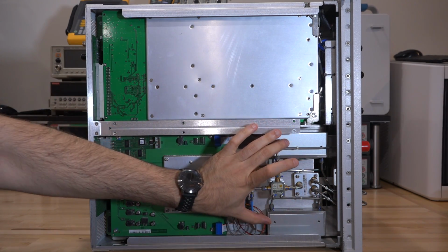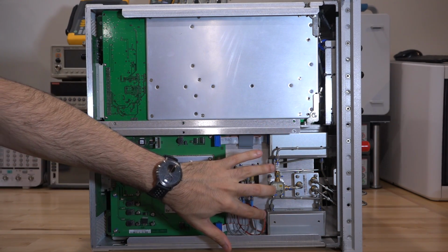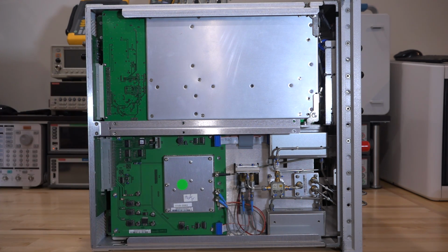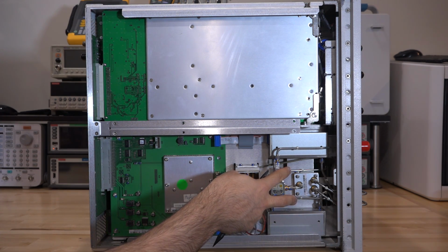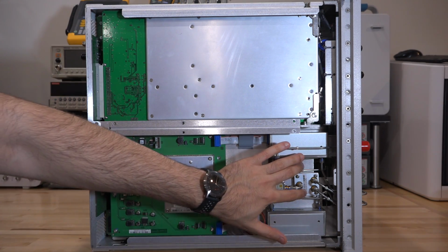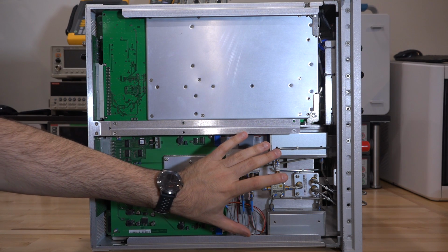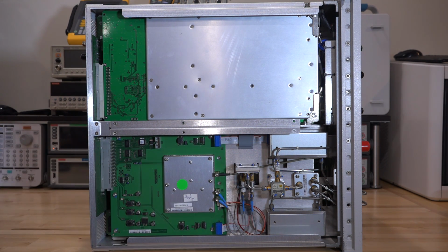But then once they come back, they go into these 2 parallel attenuators, and the outputs of the attenuators go down into the unit on the other side, where the 2 down conversions happen with 2 uncorrelated local oscillator signals. Here we have the other part going in, and we have the detection going on, that's for the power detection and all the other things which I also showed you on the block diagram. But everything coming out of these two attenuators is fully correlated to within the thermal noise of the system. What is on the other side are all the uncorrelated signals. That's why everything here is so parallelized and kept so symmetrical, in order to ensure that that happens.